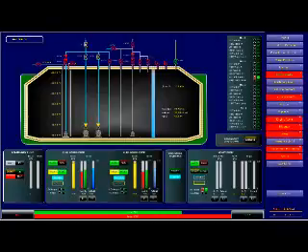Watch every single tank. That is why I was telling you that as terminal I was receiving just about 1900 cubics, and now you are giving me nearly 3000 cubics an hour. Yes, sir. So, if there is no interlock in between, like if this discharge valve is not open, this should not start. Because we throttle these valves, that is why it has got very high ampere, high load. That is maybe why earlier on it was not going on auto. You remember?